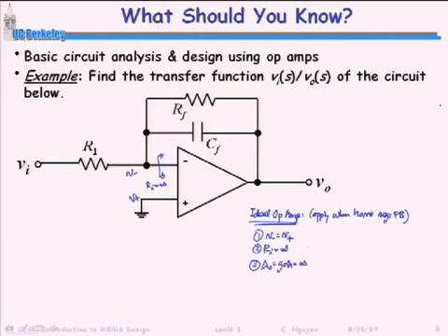All right, finally, what's one more thing? Output resistance. Output resistance of an ideal op-amp is 0. So those are the basic principles of an ideal op-amp, and you should have seen those somewhere. And as has already been mentioned up front, if you have these basic principles, if V plus equals V minus, then this node right here is going to be effectively ground. So I could take that out and do this and call that a virtual ground.